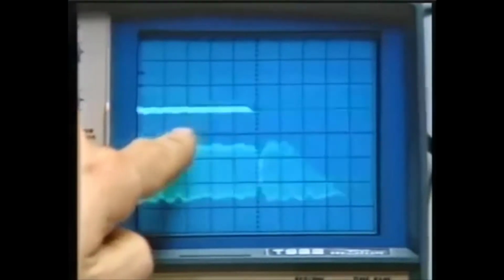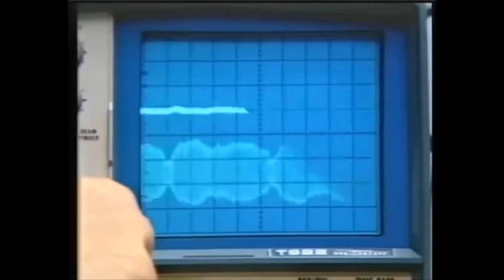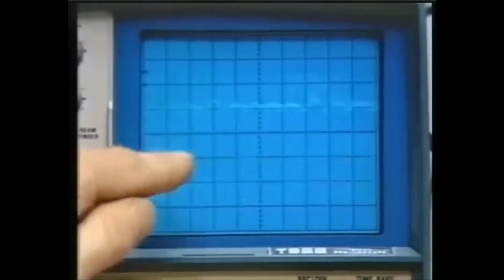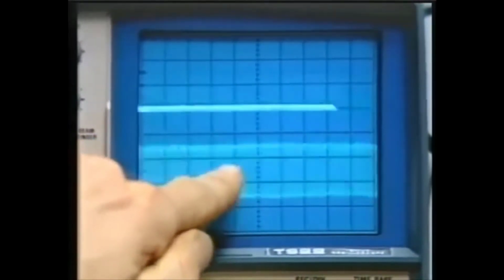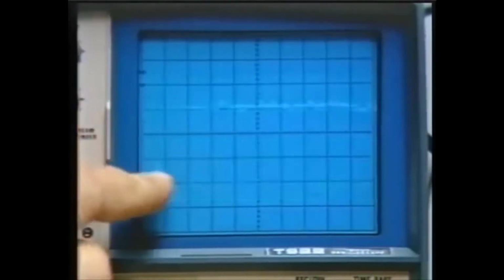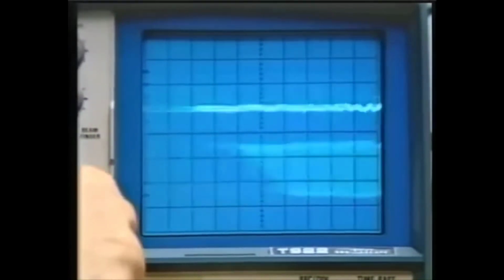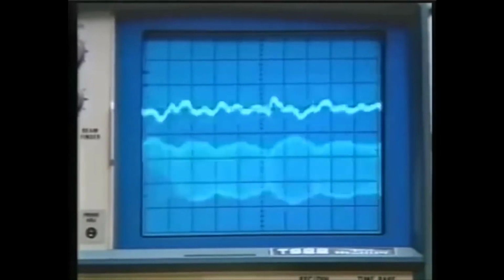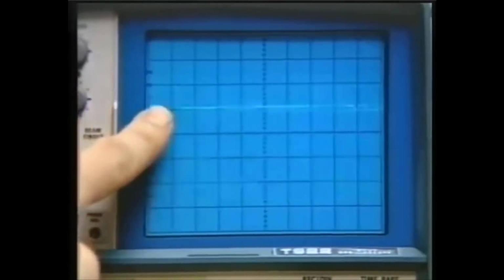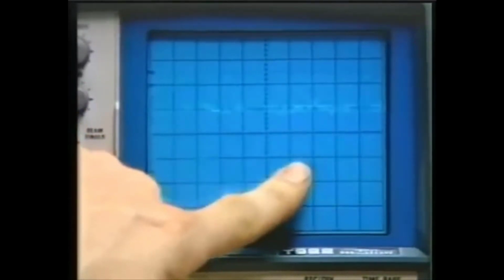And what you can see right here is the audio signal. I'll give it a little bit more gain. And this is the actual intermediate frequency modulated by the audio. And there's a correspondence between them that goes by awfully fast, but I think is pretty simple to see. So basically the top trace is the envelope of the bottom trace. That's right. This is what comes out of the envelope detector, and this is the signal into the envelope detector in this particular radio.